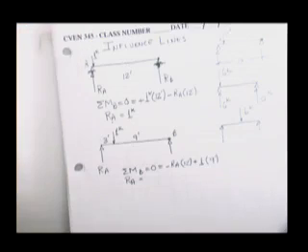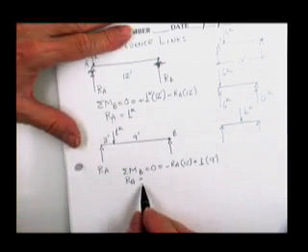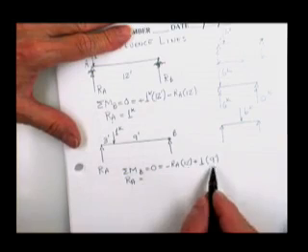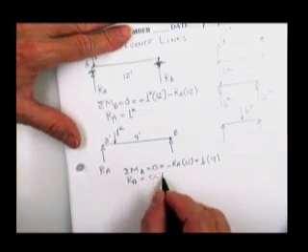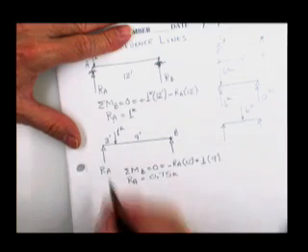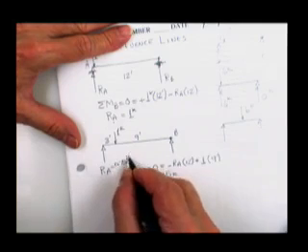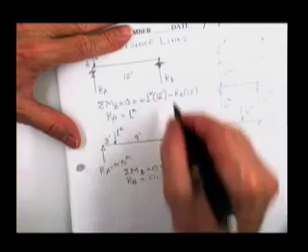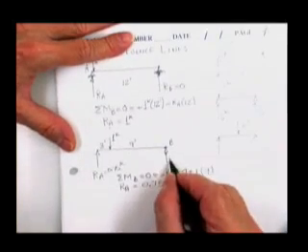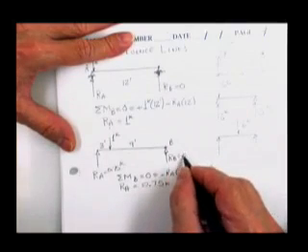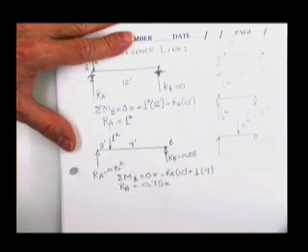Now, if you say, well, this is ridiculous, I mean, if you got a better way, show us. I will. But when these things get really ugly, I can assure you that cut, find the answer and plot it someplace will be your only hope. The reaction at A is equal to 9/12, which is 0.75. So this is 0.75 kips. And if that's true, then this reaction at B would equal 0.25 for equilibrium, sum of forces vertical.